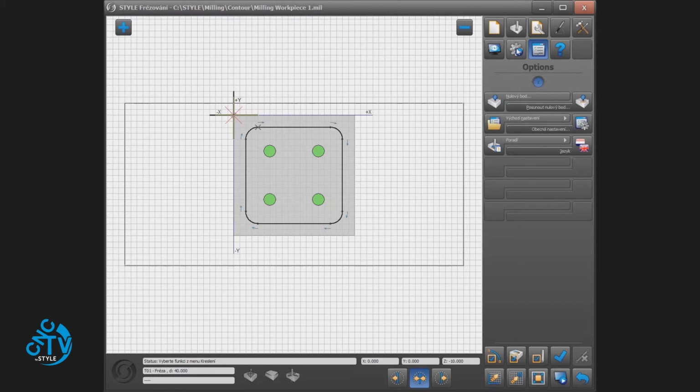When you are ready drawing the workpiece, you go to Output. In Output you can set up your machine, but before you do that you go to Simulation to have a 3D simulation of all the operations that the machine will do with this specific drawing. You can set here your tool position, you can do manual control, you can center, you can set up your safety distances, you can set the sequence of the tools, the automatic tool change. You have an origin manager, you can do repeated output, and you have your reference positions here.